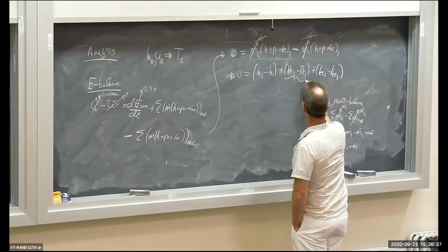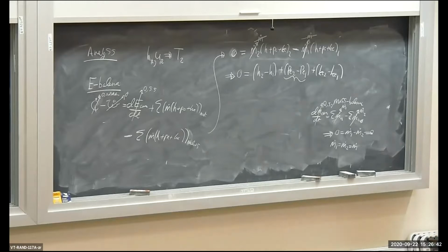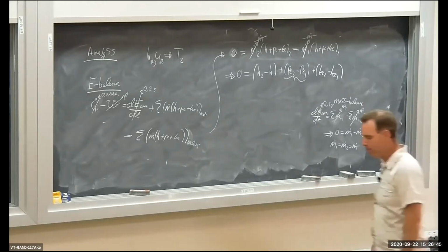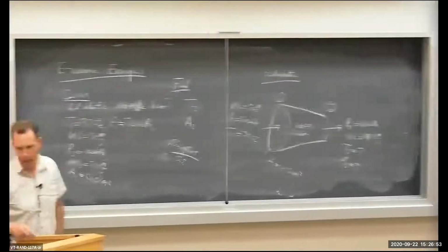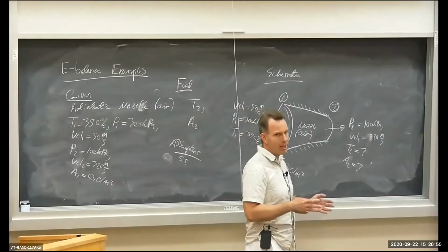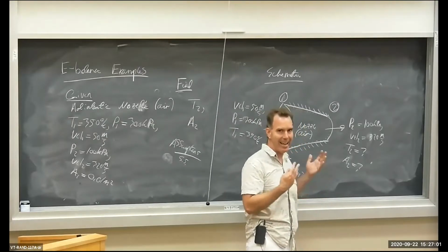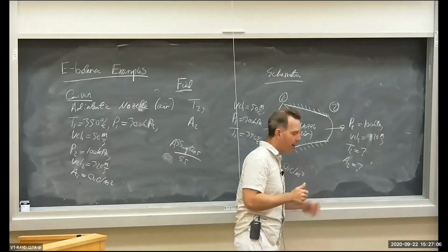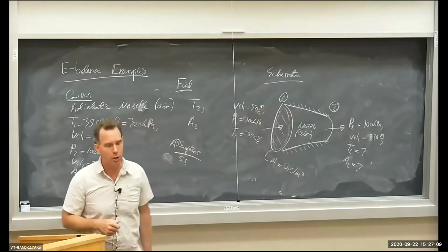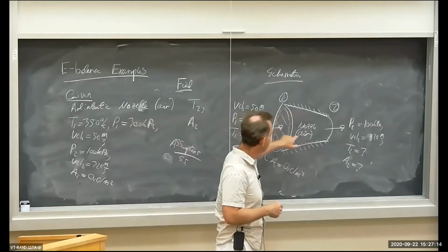This change in potential energy of the flow has to do with the average height or position of the flow. Looking back at the nozzle, the average height of the flow is not changing. And typically, changes in potential energy of something light with a low density like air, maybe not water, are quite small. But in this case, there's no change in average height between the inlet and the outlet flow.